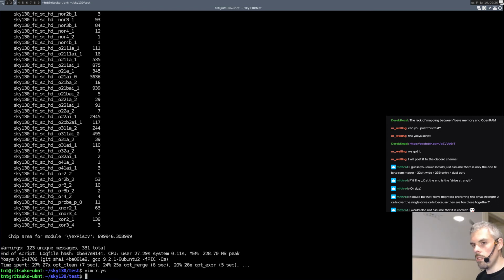Compared to this other cell, which only drives two nets, but they are at the other side of the chip, and we need to drive a kilometer wide metal layer, which is going to have a lot of capacitance. So maybe we need to boost its output capabilities. So yeah, I'm not sure who decides which cell size, which drive strength, to use, basically.